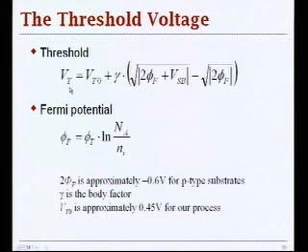So basically, it's a very simple structure. You have a gate that controls the amount of charge that can be attracted underneath the channel for conducting purposes, and then you have source and drain that control the flow of the charge, and also you have this body terminal that basically just modulates the characteristics of your transistor in a sense that it shifts this threshold voltage where you have your conductivity.